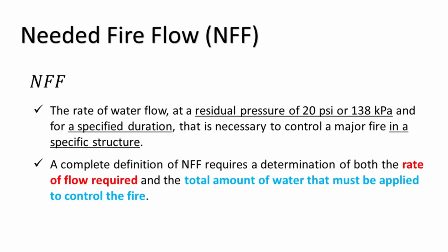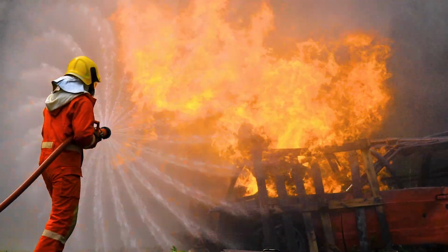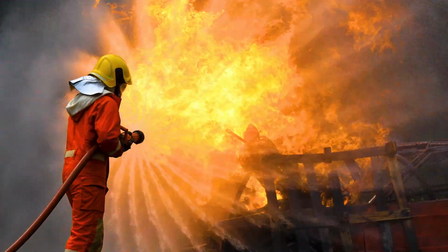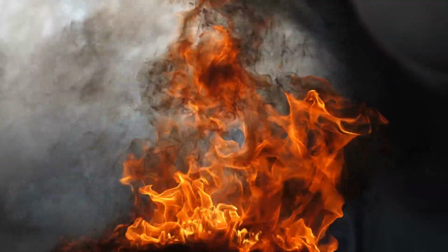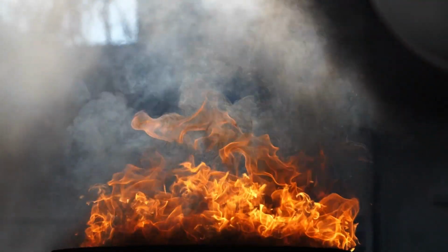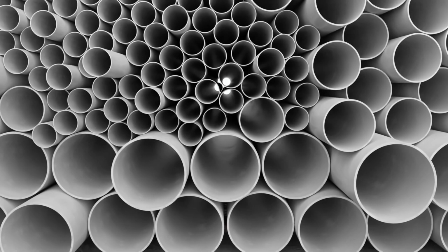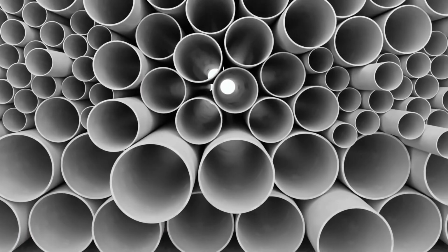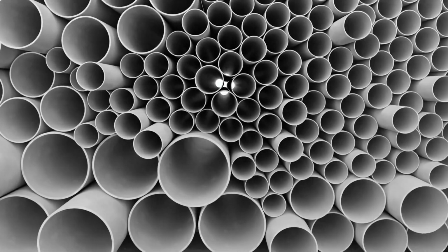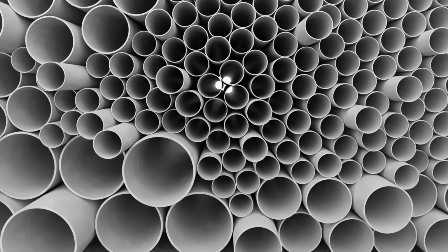4. Needed fire flow, or NFF. Many municipalities are willing to bear the increased cost of sizing distribution systems due to the potential reduction in losses achievable through utilizing the water system for fire protection. An ample supply of water can effectively cool a fire. The generated steam can starve the fire of oxygen. In situations involving miscible or dense fluids, water can disperse the fuel. The central inquiry for water utilities pertains to determining the necessary size of distribution system components to ensure an adequate water supply for fire protection.